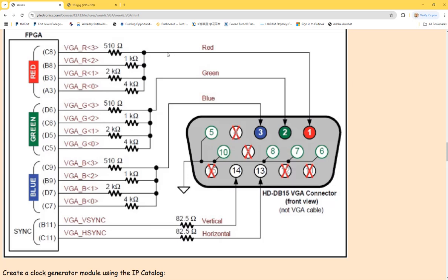So VL, how do you look at VL? VL will be the voltage dropped from here to ground. And because these are grounded, VL will be the voltage across these two terminals, right? Since this is a V in, one resistor, two resistor, this will be the voltage divider, and this one drops most of the voltage. So that is why this is having higher voltage, because the resistor here is bigger.